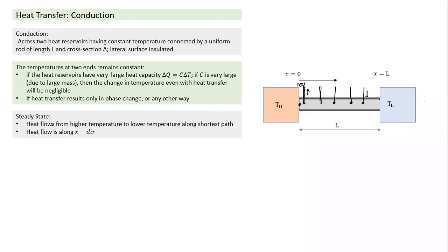So let's understand heat flow. In this case, even if the temperature has become constant, it doesn't mean the heat is not flowing. The temperature has become constant, still I find the heat will flow. If it were possible to see heat in motion, I could have seen the heat flowing from one end to the other end. But we cannot see heat flowing, we can see some other effect of heat flowing. When it reaches the steady state, if this was steam at 100 degrees, I will find that steam will keep condensing. We'll find more and more water at 100 degrees, and here ice will keep melting.